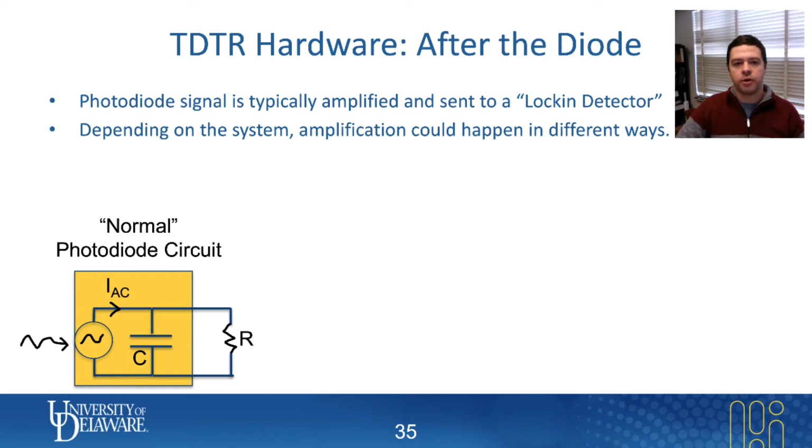All right, so I've already talked about how big the TDTR signals you expect to see are if you're just using a biased photodiode. The biggest you might ever expect to see them might be something like 10 microvolts, if you have a 1 Kelvin temperature fluctuation that you're trying to detect, and if you're using the largest possible probe signal. In reality, a lot of times that number is a lot smaller, either because you can't generate temperature